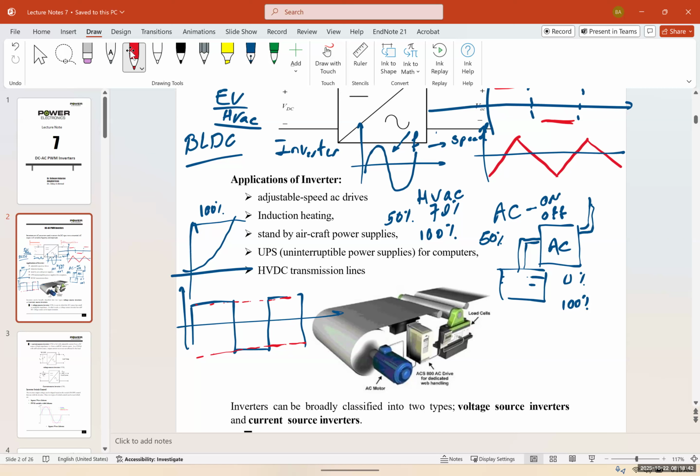But if you want to run anything that has a compressor and a motor, this may initially work. Sometimes some devices have smart meters and smart systems to detect if the input signal is not good, and it's just going to produce a fault signal. It's not going to even turn on. But the older ACs turn on, but you would see a knocking sound, okay?